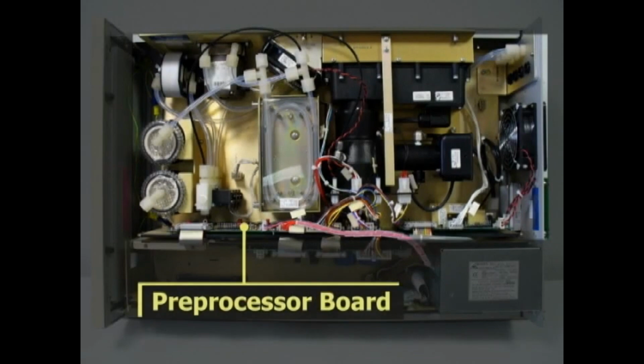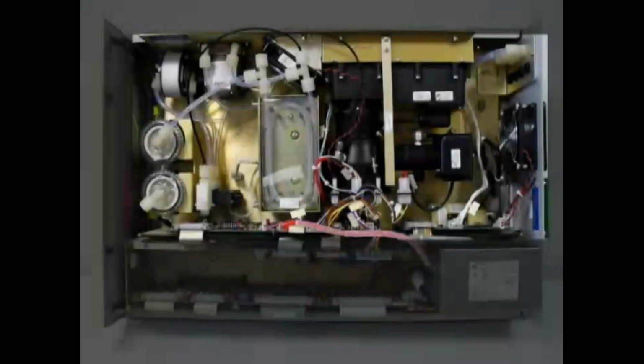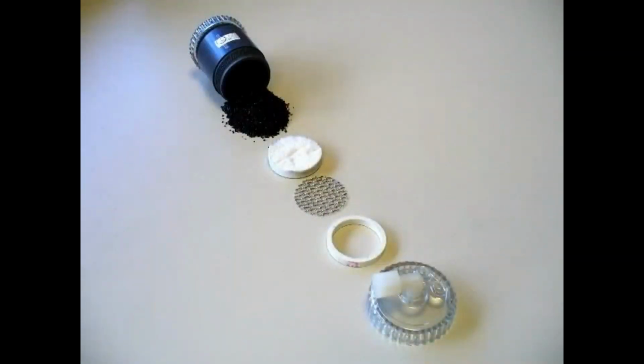The preprocessor board interfaces the microprocessor board with all the other components in the sensor tub. J5 is the test connector on this board. The kicker scrubber provides the clean air needed for kicker operation. The zero air scrubber provides SO2 free air to the analyzer for backgrounds. Both these scrubbers are filled with activated charcoal.